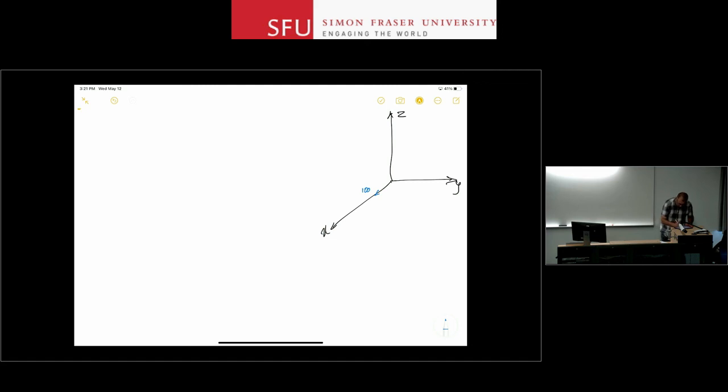And 110 is going to be 1 unit here, 1 unit here, so it's going to be in this plane. This is the 110 direction. And 111 is the one that goes from this origin out of here. So I'm just going to plot it like this. It's not easy, it's a 3D drawing that we need to have. But what I need to do is calculate the effective Young's modulus in the 100, 110, and 111 directions. So let me rewrite the formula that we had here.